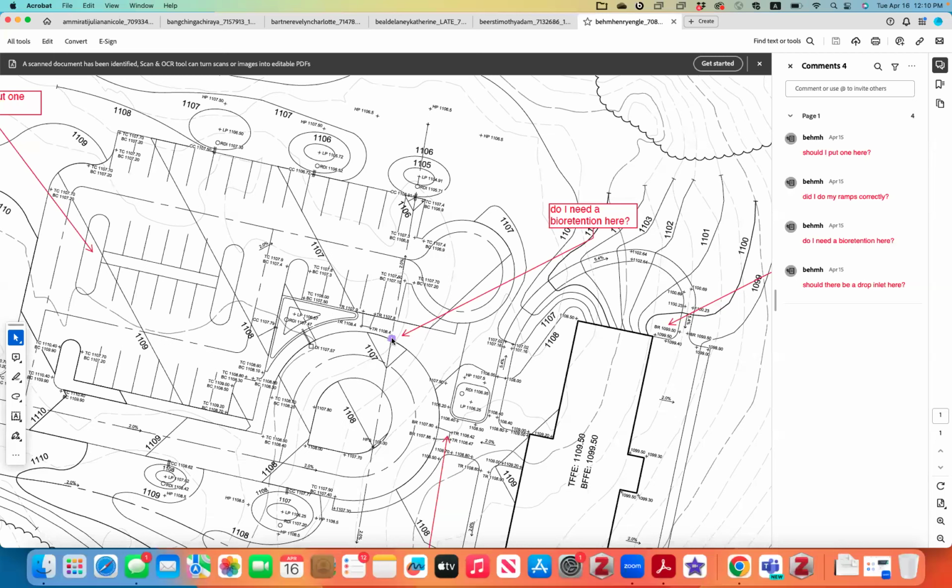This is where the water comes out. What we could do, would I just put a drop inlet there or would I put a curb cut? There's like a sidewalk in between. Yeah, well, if you put a drop inlet there, it's not treated.